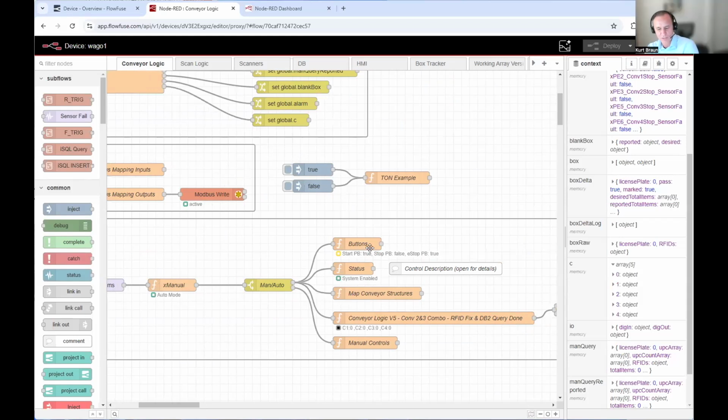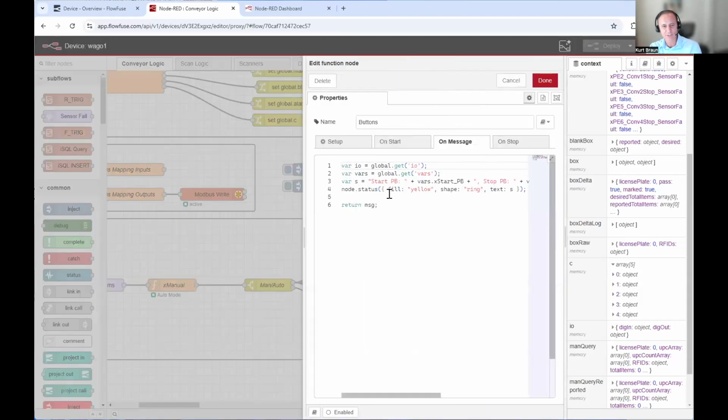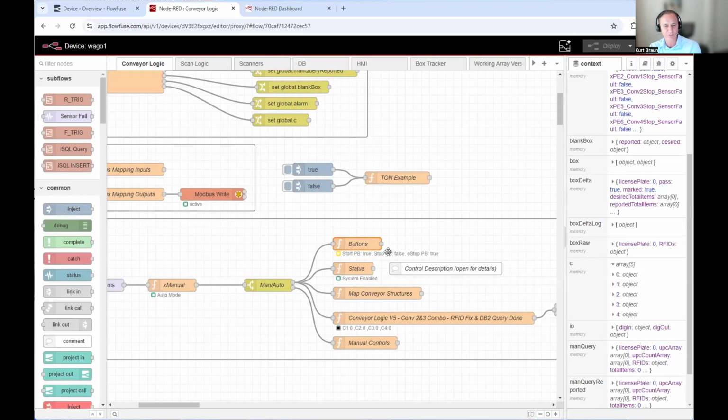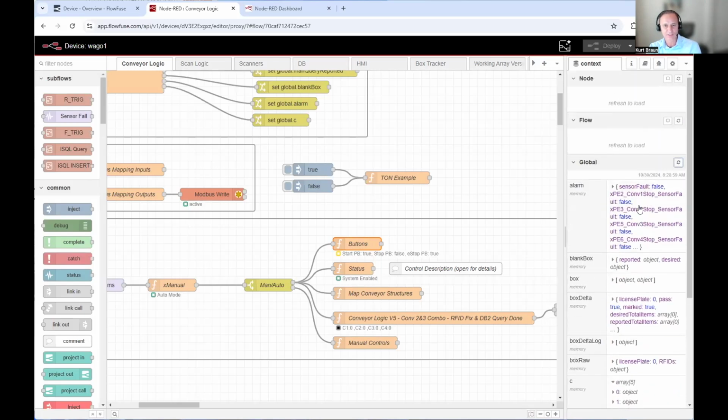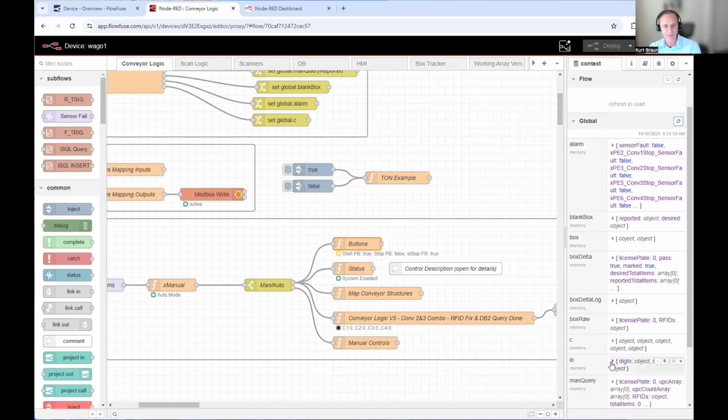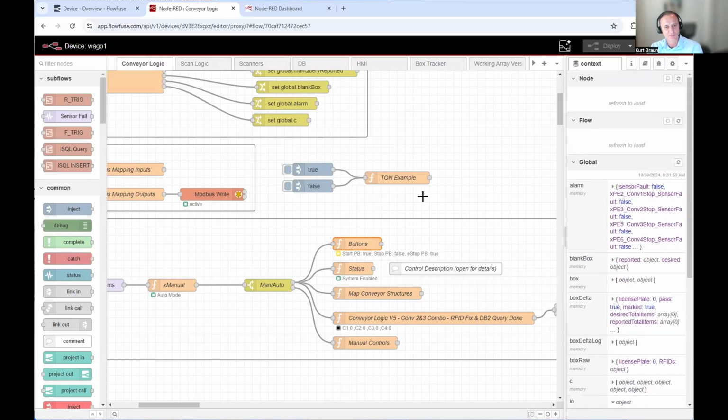Yeah, and I think controls engineers are really used to having that online mode where, when they're debugging their code, they can see the variable values all presented right in their logic. In Node-RED, especially when you're using the functions, it doesn't have a live view, so you have to either use the node status, or refresh the global list and then drill down to where the information is that you're looking for. So that part's pretty straightforward.